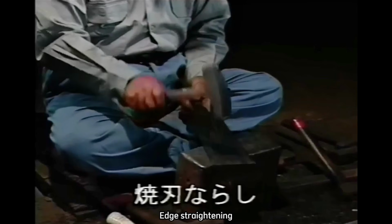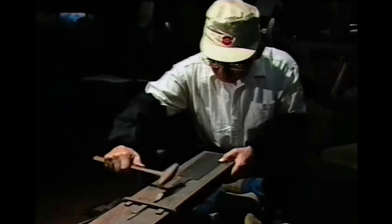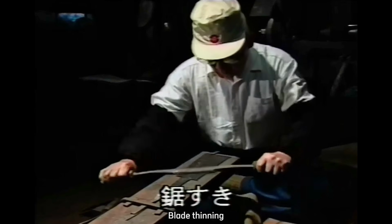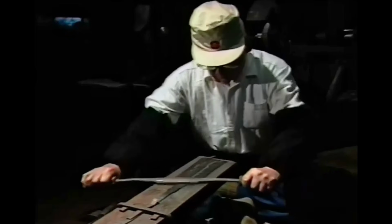Edge straightening, the process of flattening the saw, which has warped slightly during hardening. Since the blade has now been hardened, it must be hammered carefully to avoid breaking it. A tool called a sen is used to scrape and flatten the surface of the saw further. The sen work is a critical process that determines the balance of the saw.